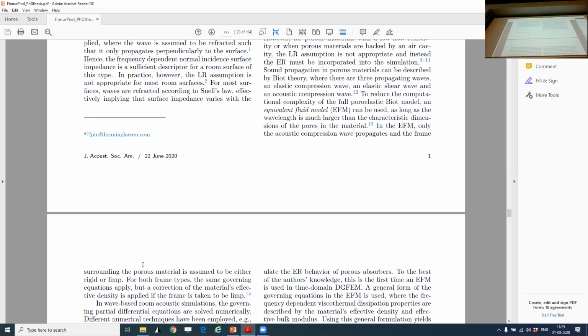If you have a room and it has a suspended ceiling, something like this here, which is very thin, and you're only simulating up to 1 kilohertz or something, then maybe the air domain elements are like this. But then of course we need these small elements here to capture this geometry, and the way we've done it, the time step is restricted. So local time stepping is the solution here. Okay. Can you show please figure 2 of this paper?